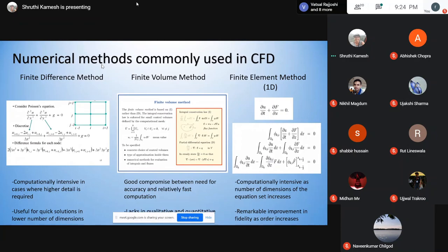So what finite element and finite volume do, in the end, is that the way these equations are simplified for finite volume that I've shown here is a sort of direct way of arriving at it, but the real way is what is shown here with the finite element method. In order to reduce the constraints that make my differential equations so difficult to solve, I reduce the constraints a bit and I introduce something called a weighting function, and I multiply it with the equation.